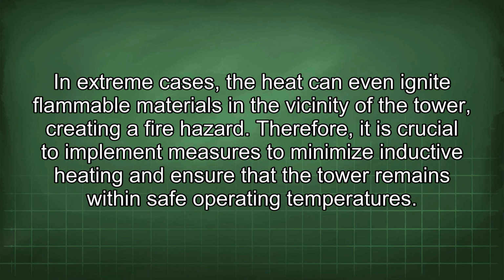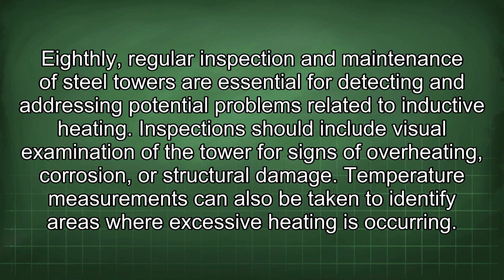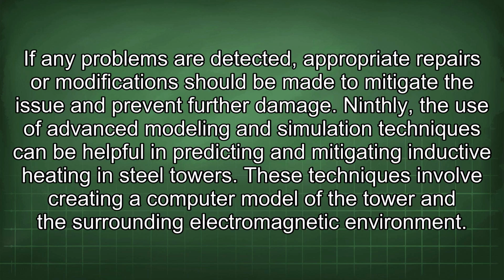operating temperatures. Eighthly, regular inspection and maintenance of steel towers are essential for detecting and addressing potential problems related to inductive heating. Inspections should include visual examination of the tower for signs of overheating, corrosion, or structural damage. Temperature measurements can also be taken to identify areas where excessive heating is occurring. If any problems are detected, appropriate repairs or modifications should be made to mitigate the issue and prevent further damage.